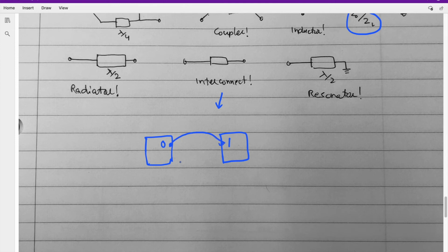Let's say they have ground, so somehow you come up with a way of ideally grounding them. Their grounds are connected ideally, and the signal is just connected following this one path. Now at lower frequencies, this is okay. This is what you do. You just put a jumper wire between these points and then they get connected.